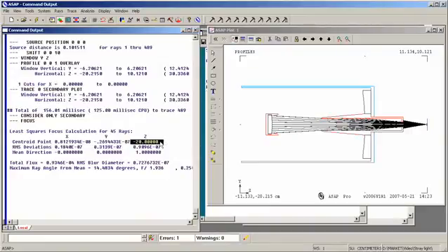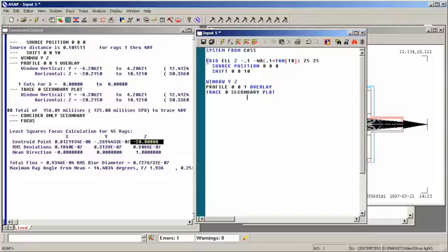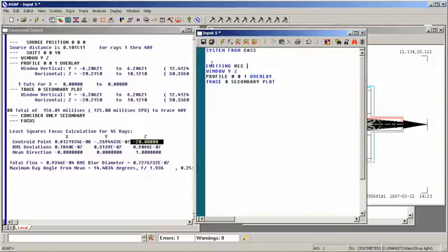We now need to find out the size of that image. We're going to use the same idea, but we're going to use an extended source, not a point source. Instead of our grid, we'll use an emitting rectangle. We'll again place it on the detector, actually just slightly off of it. The size is the same. That is to say, the detector dimensions are 0.15 by 0.15. Same thing. And we have to tell it how many rays to trace.